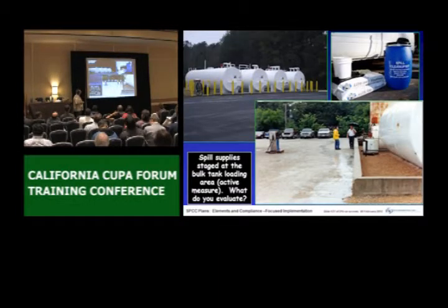All right, anyway, just an example of realistic. This is the navigable water out here down in the creek, right? And is a spill kit likely to be believable as general containment for loading in this area? That's pretty close. I'd question it. So again, look at the criterion in EPA's Appendix G. Take a look at that.